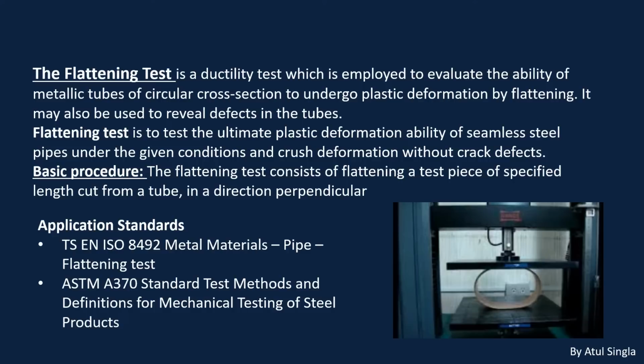The basic procedure in this testing is that the flattening test consists of flattening a test piece of specified length cut from a tube in a perpendicular direction. If you look at this picture, we have a particular piece of pipe which is pressed in a perpendicular direction.